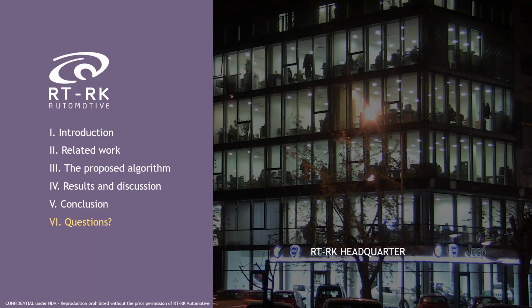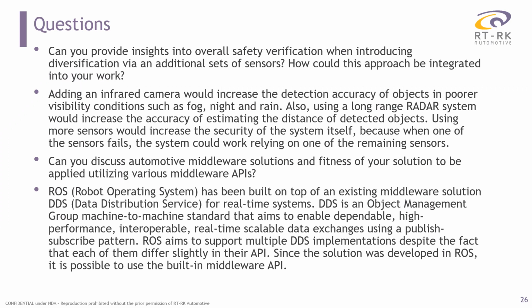In the next topic, I would like to answer a few questions. Can you provide insight into overall safety verification when introducing diversification via an additional set of sensors? How would this approach be integrated into your work? Adding an infrared camera would increase the detection accuracy of objects in poor visibility conditions, such as fog, night, and rain. Also, using a long-range radar system would increase the accuracy of estimating the distance of detected objects. Using more sensors would increase the security of the system itself, because when one of the sensors fails, the system could work relying on one of the remaining sensors.